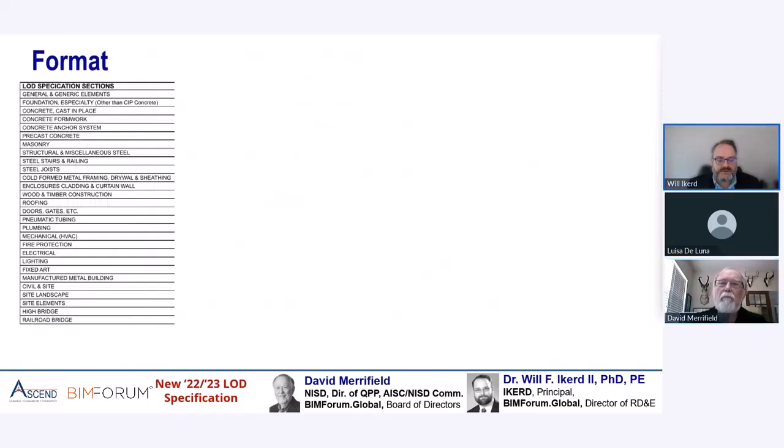Right. And so just within steel, you could have potentially 5 companies with 5 different modeling teams, and things such as bar joists are almost never at LOD 400. And I want to repeat that. They're almost never at LOD 400. The reason is that if you're welding on those bar joists, the second that bar joist leaves the factory, it is no longer the responsibility of that manufacturer. That's a manufactured product leaving one stakeholder that took their model to LOD 350 in many cases. Then the erector is placing those bar joists and welding them on, and they're putting the miscellaneous steel out into the field.